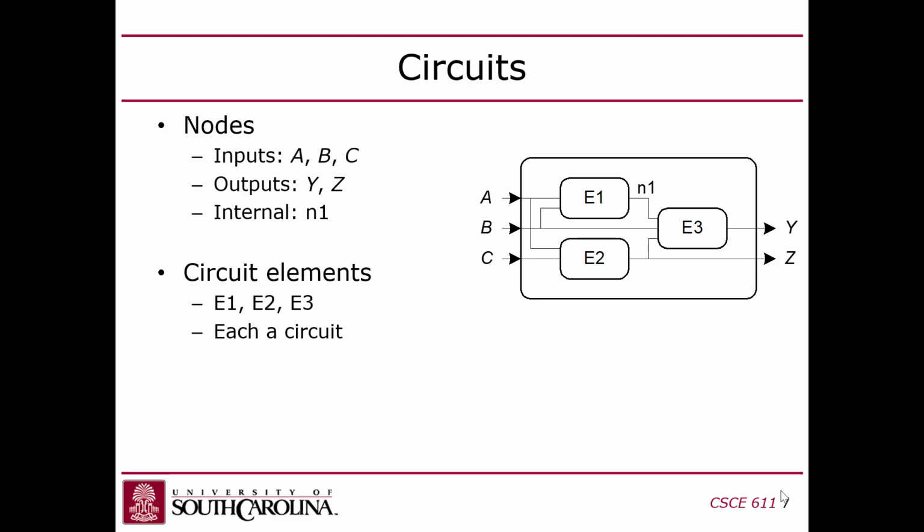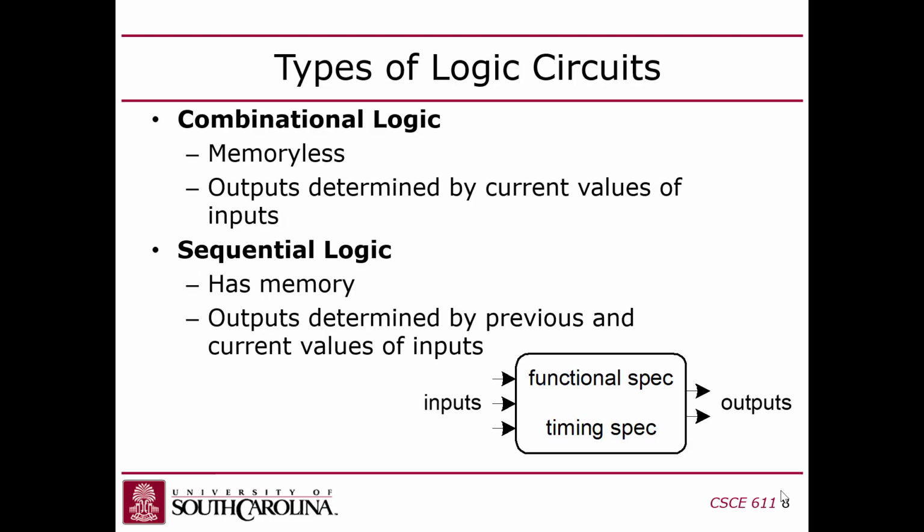Now, what confuses me sometimes is, wait a minute, hold on. What about this T connection? There's no dot there, but yet A is shorted. This is a connection where it T's, but this is not a connection where it crosses. So to this day I still sometimes get thrown off by that. So a T connection is connected, a cross is not, unless there's a dot. That's a good question. There's a slide here that addresses that too.